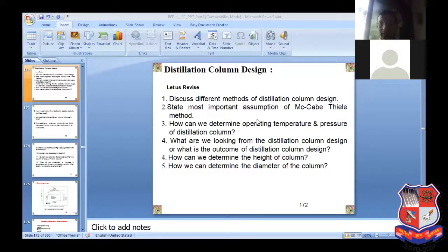Like heat sensitive materials, when you operate with heat sensitive things like fruit juices, fruits, medicines, or other components which are going to degrade when exposed to a high temperature. Fine, like crude oil distillation. Whatever petrol and diesel we are getting, that is coming from the refinery. Refinery operations involve an atmospheric distillation unit as well as a vacuum distillation unit. The bottom product of the atmospheric distillation unit reaches a composition where its boiling point is almost 340, 350, more than 350, 400 degrees centigrade.